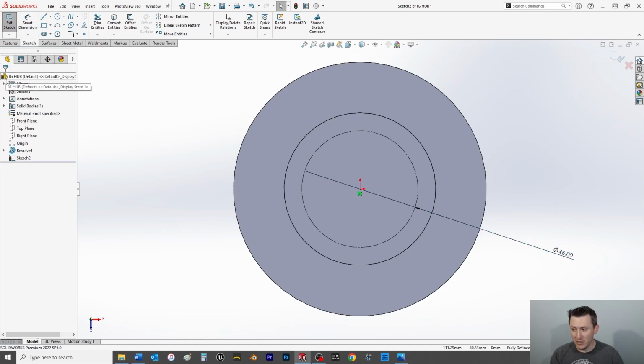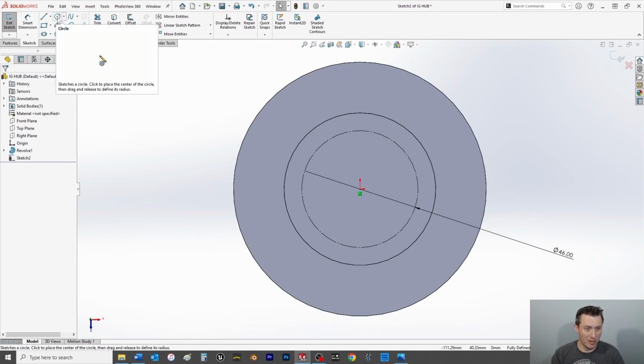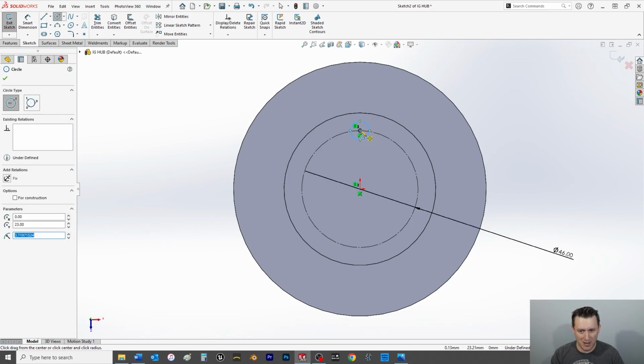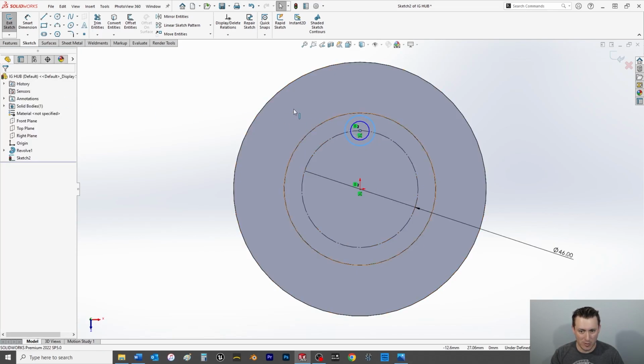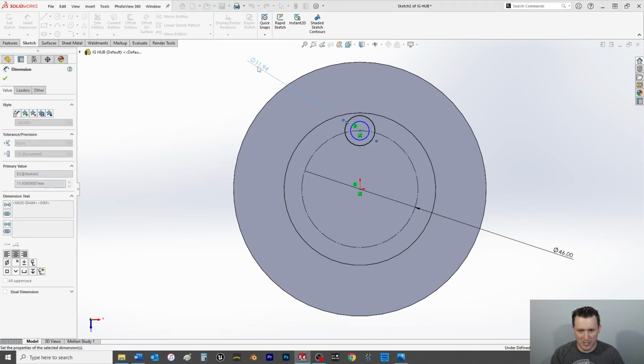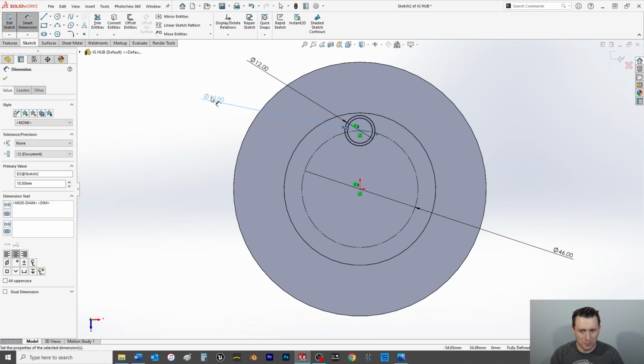And then from here, we'll create our circle, ribbed circles specifically. So we're going to grab a circle again. We're going to come up here. We're going to make sure that we're coincident in the circle and then also have a vertical relation. Click, drag out, do that twice. We need 2 circles. This gives us our rib profile here. OD, 12 millimeter, ID, 10 mils.